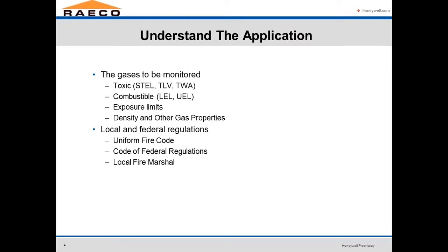For combustible gases, we're looking at the LEL, or lower explosive limit, and UEL, upper explosive limit. Also, make sure that you understand other properties of gases, such as the density, whether these gases are lighter than air and will float, or heavier than air and will sink. That will also help determine sensor placement within the facility.